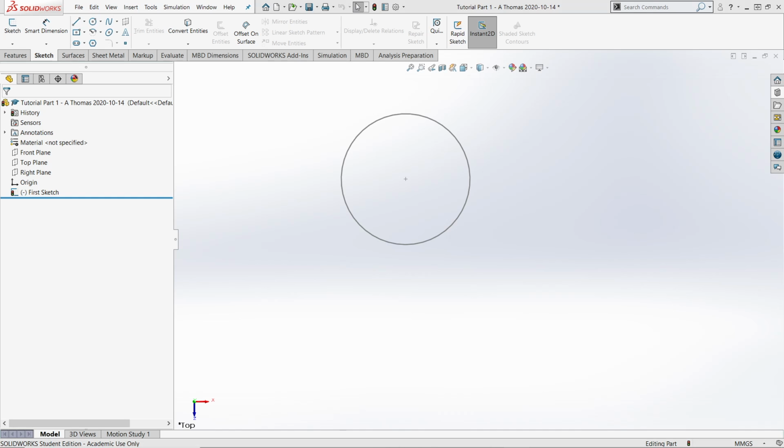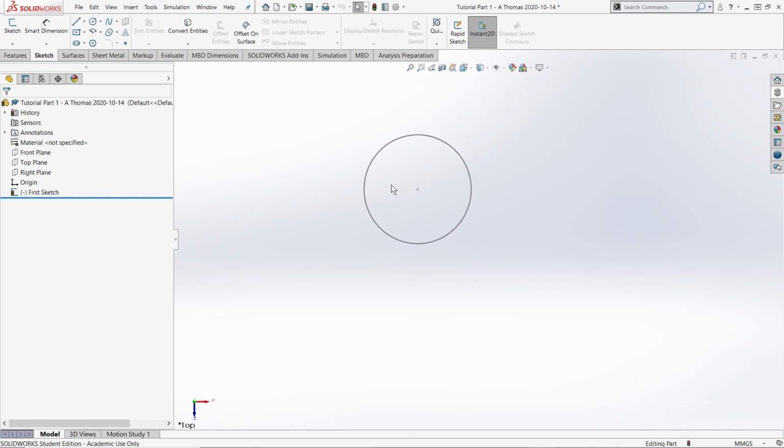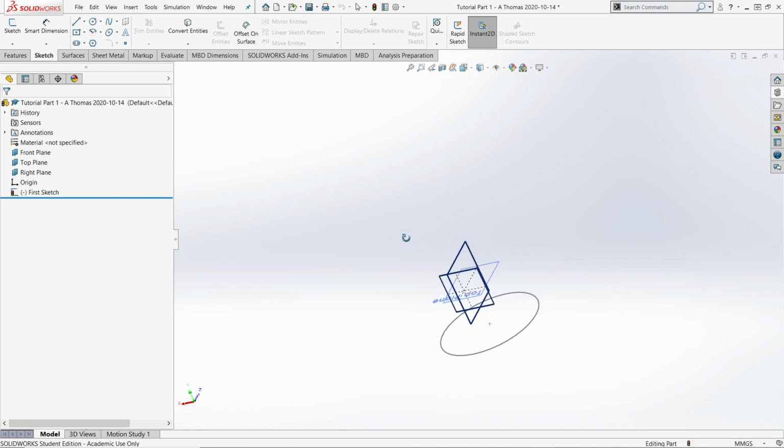So next I'm going to talk about navigating in 3D in SolidWorks. If you haven't used a CAD program, this might be weird. I'm going to turn on the primary planes using that heads up view icon thing. If I hold the middle mouse button down and then move my mouse while that's selected, I can orbit, is what it's called in CAD programs. So holding middle mouse button and dragging the mouse makes me able to rotate everything that is in my CAD part.